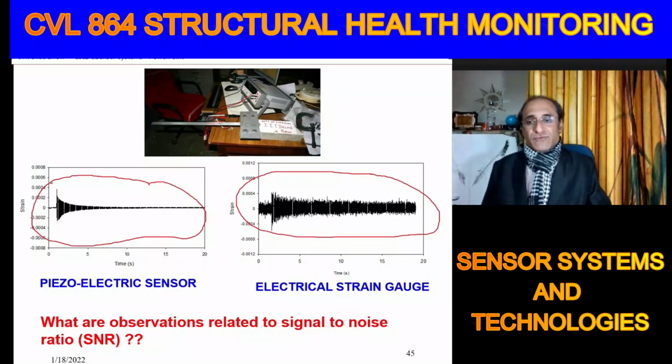So basically we were doing the measurement like this: we started taking measurement at time 0, and then at about 1 second we hit the cantilever beam into vibration. So this is what happens, that strain is high, and then slowly the vibrations die down. So this process can be very easily captured for a very long time.